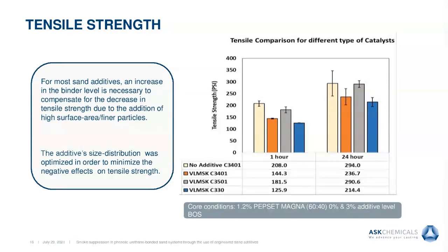So we don't want to fall in that cycle. So the idea is that we can recover the tensile strength by just adjusting the catalyst or the type of catalyst. And we also found some catalysts that didn't work very well. So if we do this in some customer or facility, we will have to work closely to determine the most ideal conditions for catalyst and binder to get the best results we can obtain.